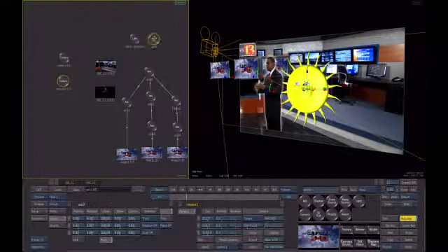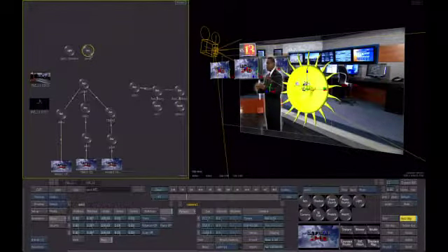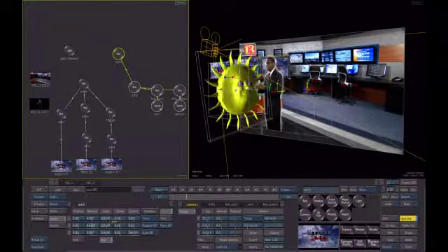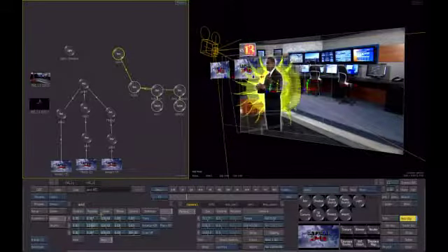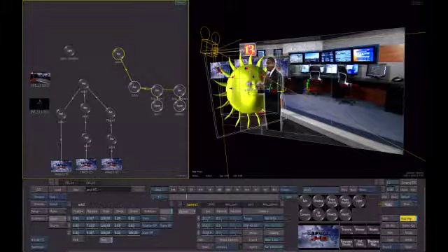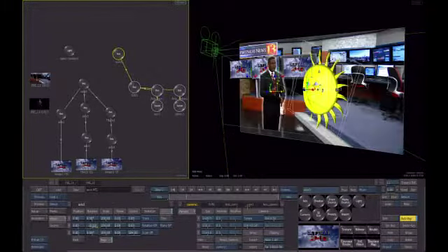And watch how easily you can do this. I'll just bring an axis into our scene, and I'll parent it to, not that one, let's see, to that one, the layer that controls the sun there. And I want to offset that, so I'll just take the center point, and you can see I can bring this right up to where he is. You can see the axis moving there on the right. And then that gives me the ability to start rotating and spinning this around. So a really simple trick, but you can see it's taking advantage of the fact that that's set out in 3D. And what I'll do is go back to frame 1 and set a keyframe, go to the end and set a keyframe.